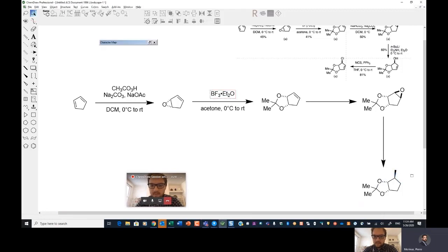You cannot just sprout a bold bond from an atom. So you'll need to create an atom and press B over the bond to make it bold, as opposed to W for wedged. B, and that's the difference.